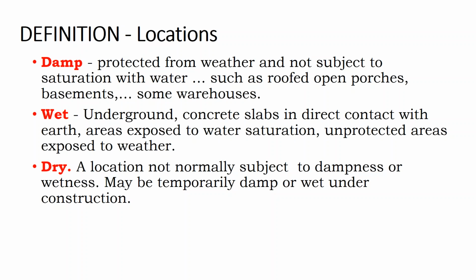cable that's used outdoors by the utility on high voltage systems, like a feeder cable that comes into your building, that can be high voltage, that can be exposed to the sun, that can be in a hot temperature, that can be in a wet location. So why can't you use utility feeder service entrance conductors instead of PV wire? What's the difference between those two cable types? Well, you might find that both cables are listed for a wet environment. And what can be confusing is that these cables can be cross-listed, so they can be listed for a wet environment and a dry environment.